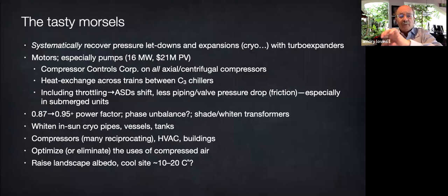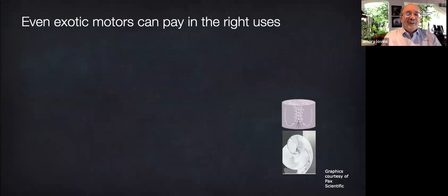By the way, the pipes themselves, the cryogenic plumbing, those were all beautifully sheathed in shiny stainless steel. So I pointed the infrared thermometer at one of those too. A little thought experiment. If you take 3 pieces of sheet stainless steel, one bare metal, one painted black, one painted white, and you stick them all in the sun, which will get hottest? Probably the bare one, because stainless steel has very poor infrared emissivity. Even black paint probably runs cooler, but white paint costs the same. It's just physics.